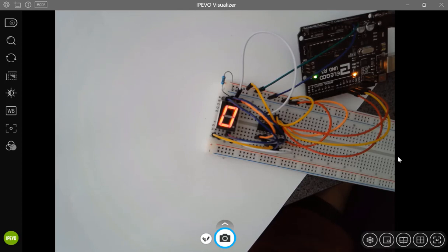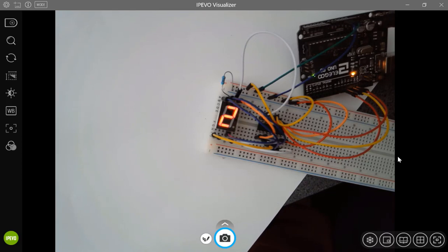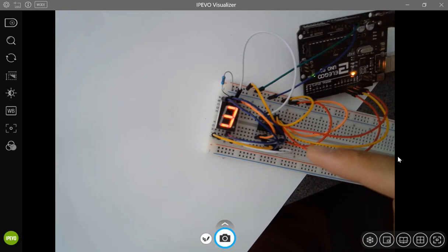Also, if you want to display a complicated number, a series of numbers, you probably need a dedicated driver for it. We're not going to use a driver for a complicated project in the future, but you have to take this into consideration when designing a digital system. This is a basic 8-bit CPU with only one core, and that core is occupied doing this display only.